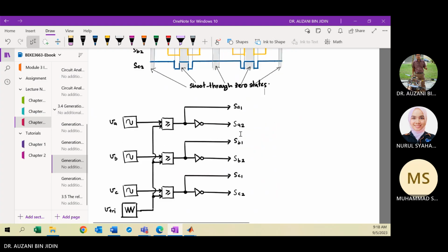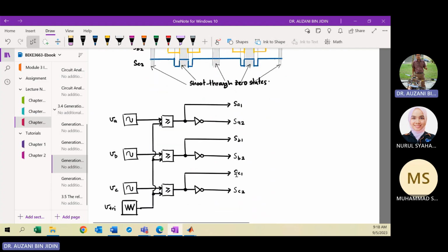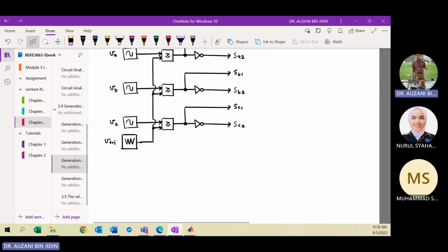So for the Z source, because you have the shoot through here, how to construct the circuit? In order to model this condition, the shoot through can happen when, maybe green color, VP is less than triangular, or VN larger than triangular. So you see the operator OR here. It can be either the first condition fulfilled or the second, then it will produce 1. Okay, clear?